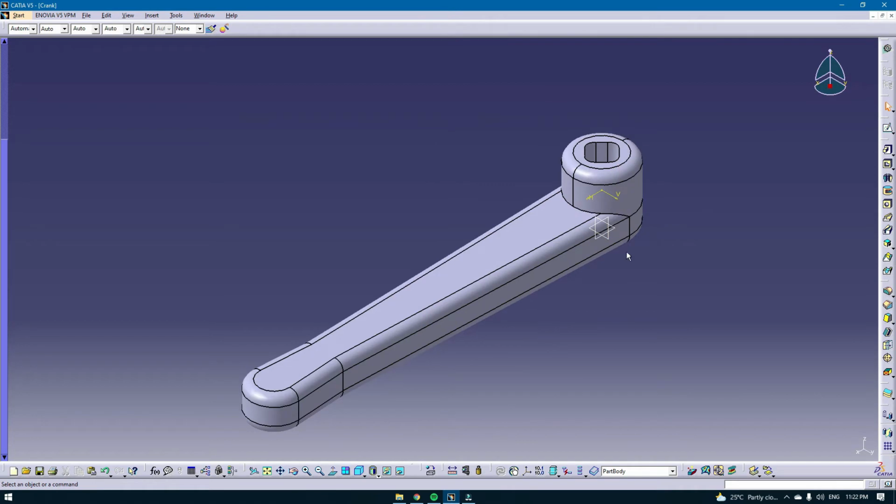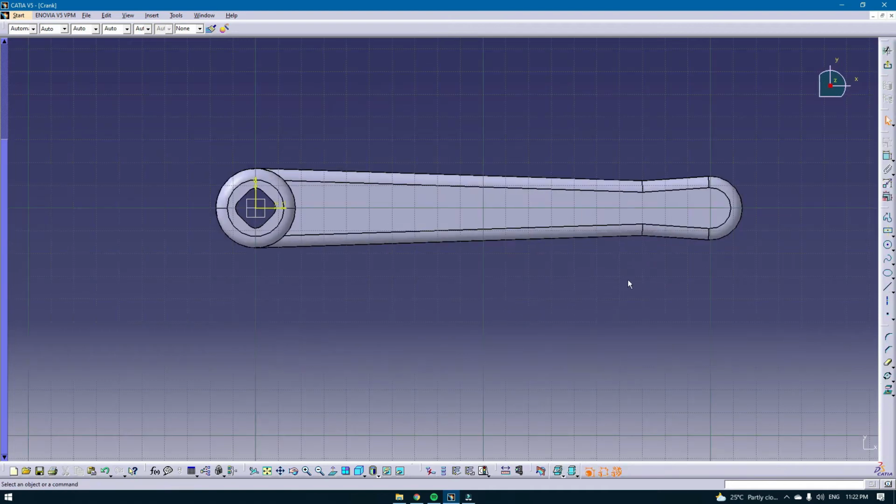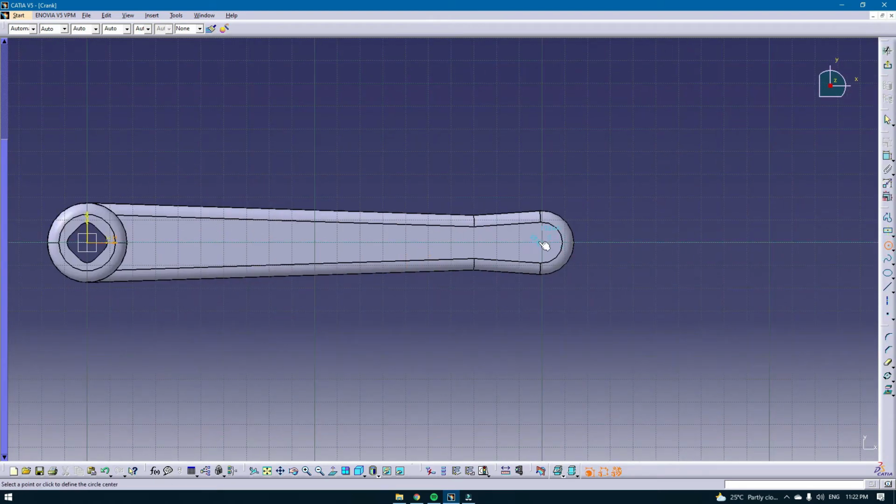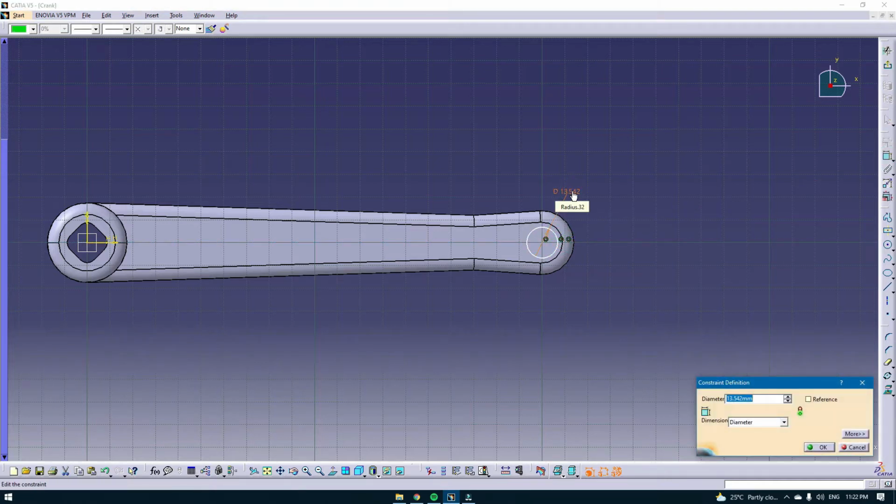So we got the rectangle fillet. Then next we will do another circle. We sketch on the top and make one more circle, with a diameter of 50.